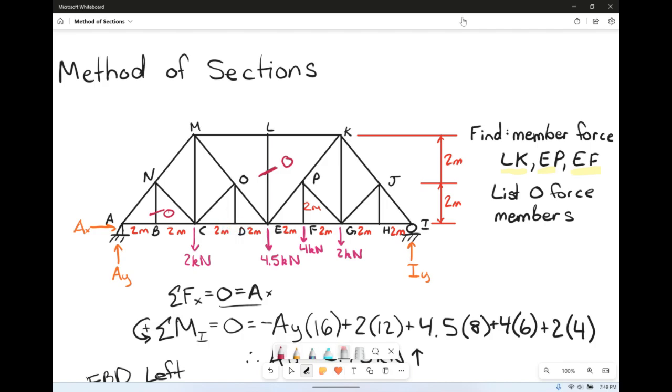So at joint D, this is also 0. And at F, you might be thinking, oh, we can do the same thing, but actually at F, we have a downward force. So in this instance, no, that one is a little bit different from the rest of them. But if you go look at joint H, he is the exact same as everybody else. He's a zero force member.